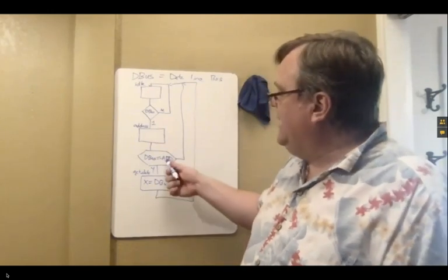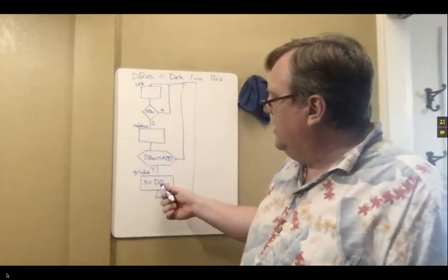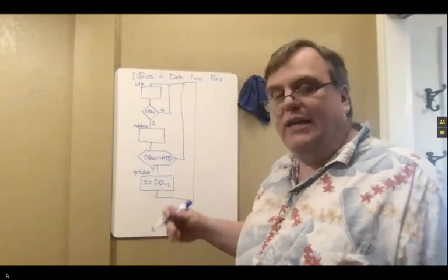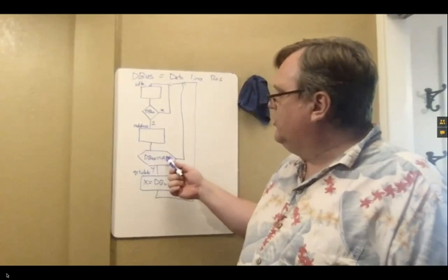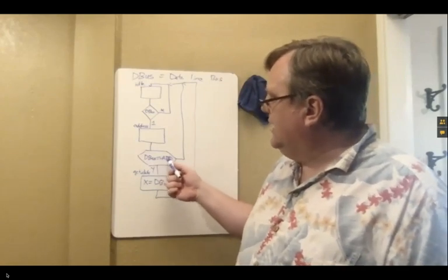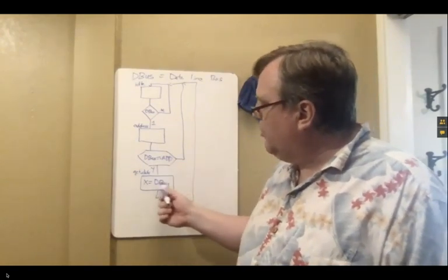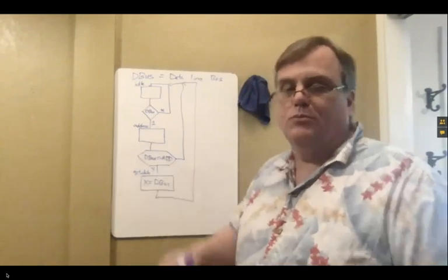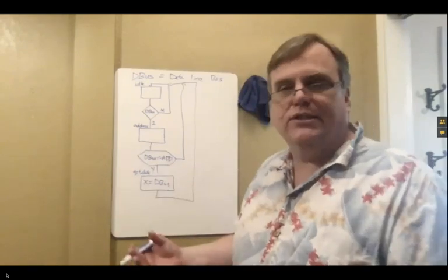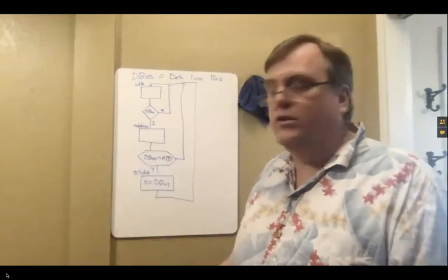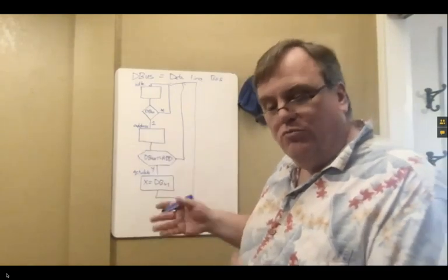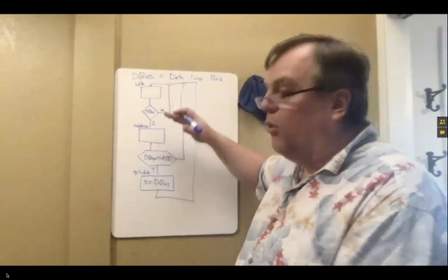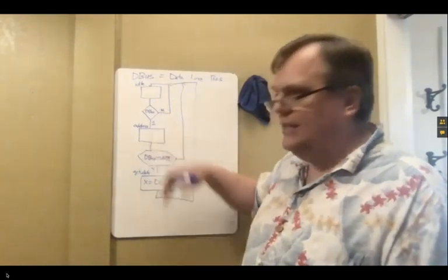And often the address and the actual data are sent in parallel. So there's often, say, 32 or 40 bits that are dedicated to the address, and then there are 64 bits dedicated here, then some control bits. And the total mess is like 128 bits coming across, and I do it all in one cycle. So for really fast buses, we give you more wires so you can take fewer cycles.